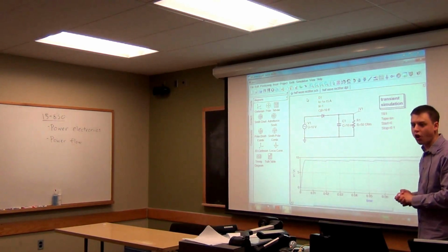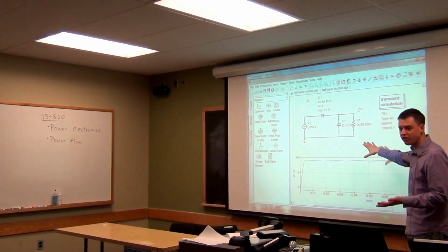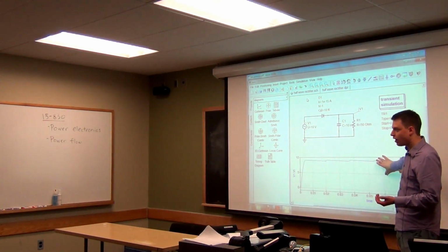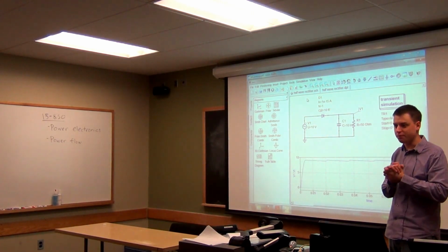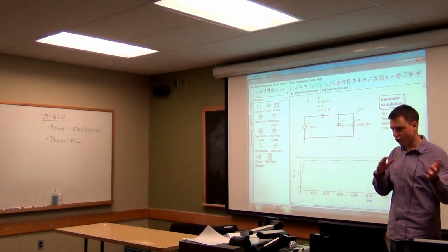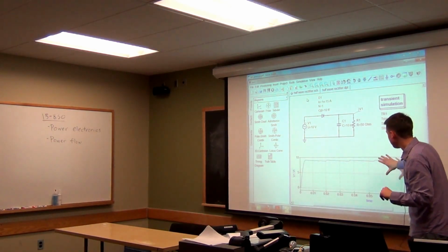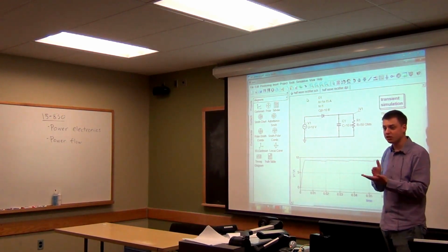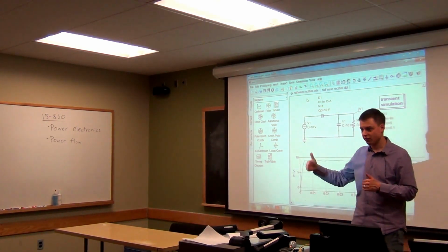Now, the reason why this took longer to simulate than the other ones you saw is that the only way to simulate this really is to actually build the dynamical system equations of what's happening in this circuit. Remember, the capacitor's law relates the derivative of the voltage and the current. And so it sets up a dynamical system that has all these elements in it, and then just steps through integrating this forward in time.